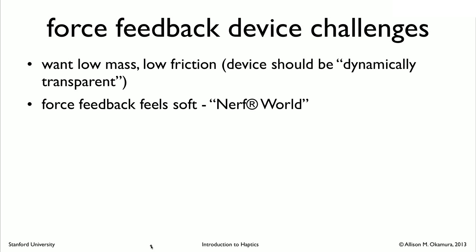Other things that limit the hardness of a virtual wall, say, that you create with a haptic device is the fact that there are very small time delays in the system. You have to measure the position, you have to compute what force to output, and then the haptic device actually has to output that force.